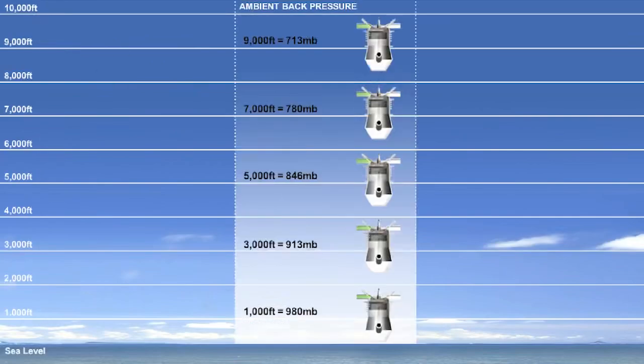There is, however, one bonus which can be gained through climbing the aircraft. The ambient pressure decreases as the aircraft climbs, and it is this ambient pressure, or back pressure, which resists the escape of the waste gases from the cylinder during the exhaust stroke. It is this same pressure which dictates that the piston has to waste energy in driving those gases from the cylinder during the exhaust stroke.